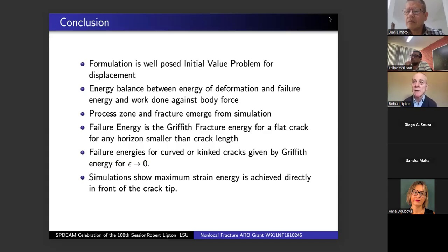So this is the wonderful thing. Your crack modeling is only as good as your elasticity modeling. So the elastic field can be used to guide the crack. One crude way to generate an elastic field is through body forces, creating different scenarios for elastic forces to occur in response to a load. And that way you guide a crack. The other way that I know of is to introduce an inclusion by itself. By its very geometry, it will induce a stress field which can then be used to influence a crack.